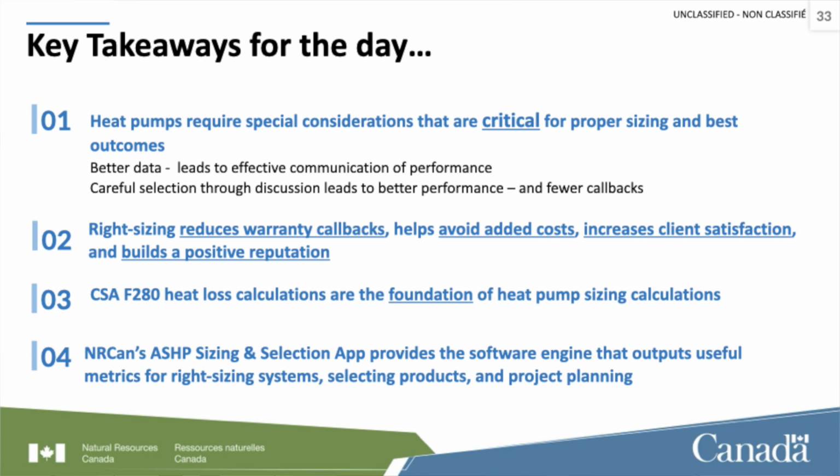Look at that. So heat pumps require special considerations. I think we all agree on that. There's a certain amount of training that's required of the homeowner, and a certain amount of training that's required for the people that install it. But better data leads to a better result. Right sizing reduces warranty callbacks, helps avoid extra costs, and increases client satisfaction because we're not short cycling and they're comfortable in all rooms. It builds, like I say, I don't know if it builds a positive reputation, but it keeps you from losing it anyway.